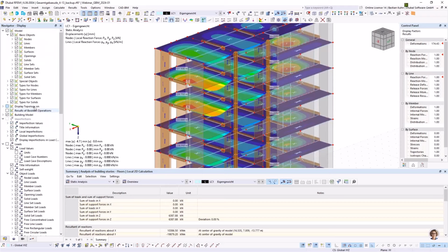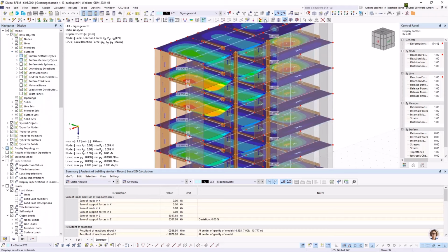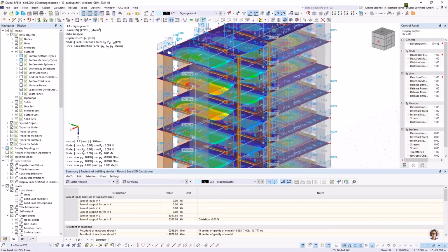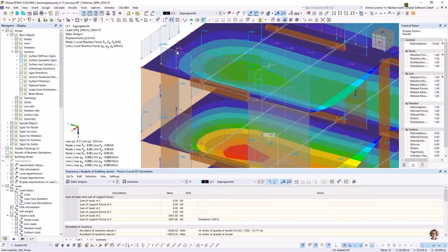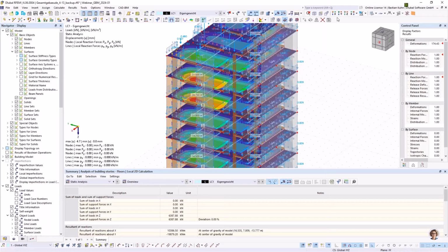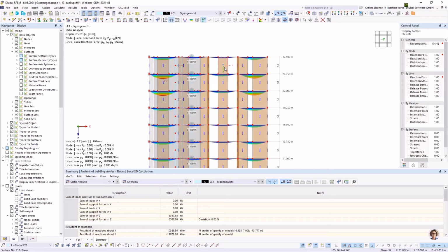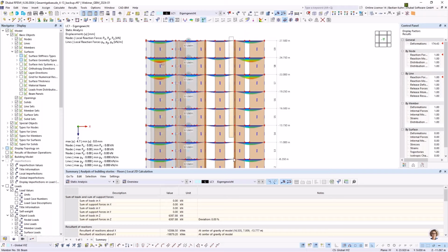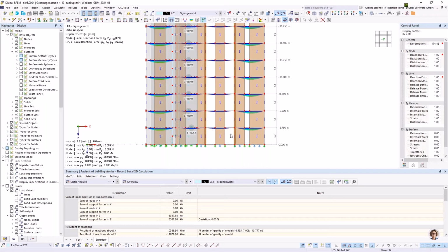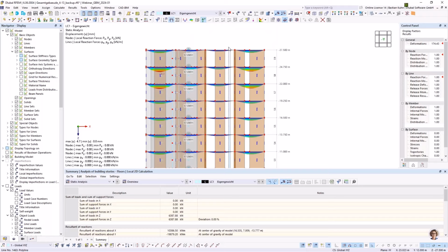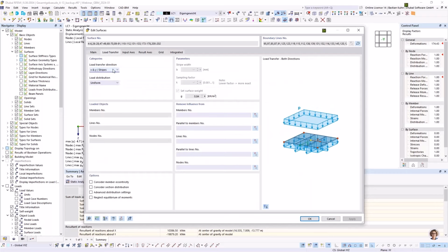And when we activate the functionality surfaces and loads from distribution, you can see now here that I have a constant force in here, which is actually what we want. But when we switch back, the reason is because I changed these slabs already from the isotropic to the varying point, and I would like to show you the effect again, what this is doing. All right, so I change these 30 surfaces and go back to the standard isotropic FEA stuff,